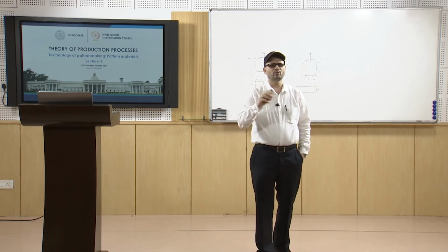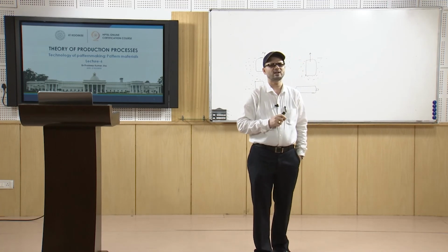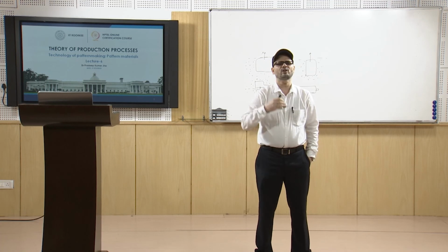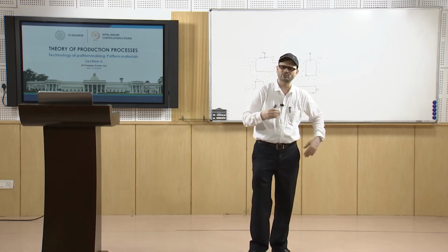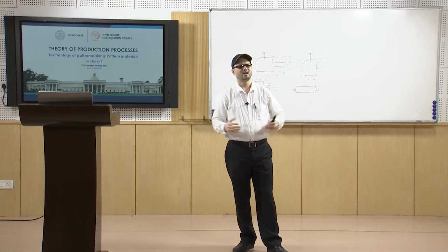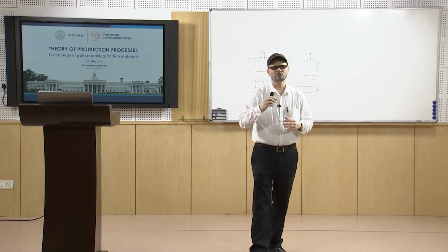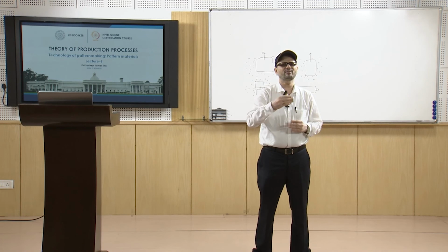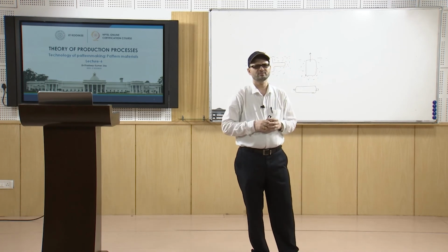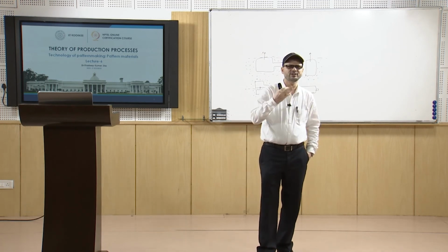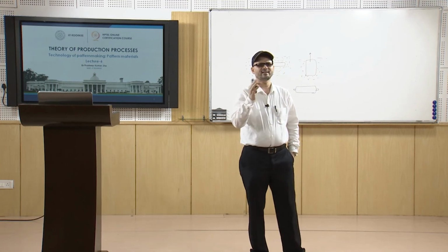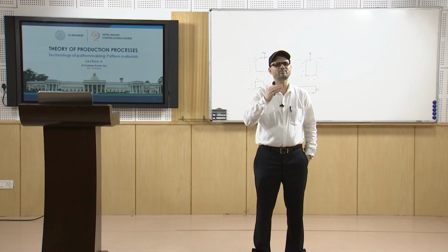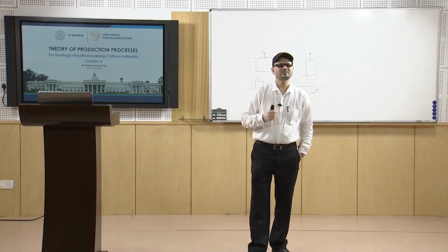So, you have both thermosetting and thermoplastic materials used as patterns, and thermosetting plastics are used for making long lasting and durable patterns. As we know, thermosetting plastics have good strength, and for shorter runs you use the thermoplastic materials. In the thermosetting variety you have epoxy and polyester resins. In the thermoplastic type you have polystyrene. Silicon rubbers are also used for dies in special cases.